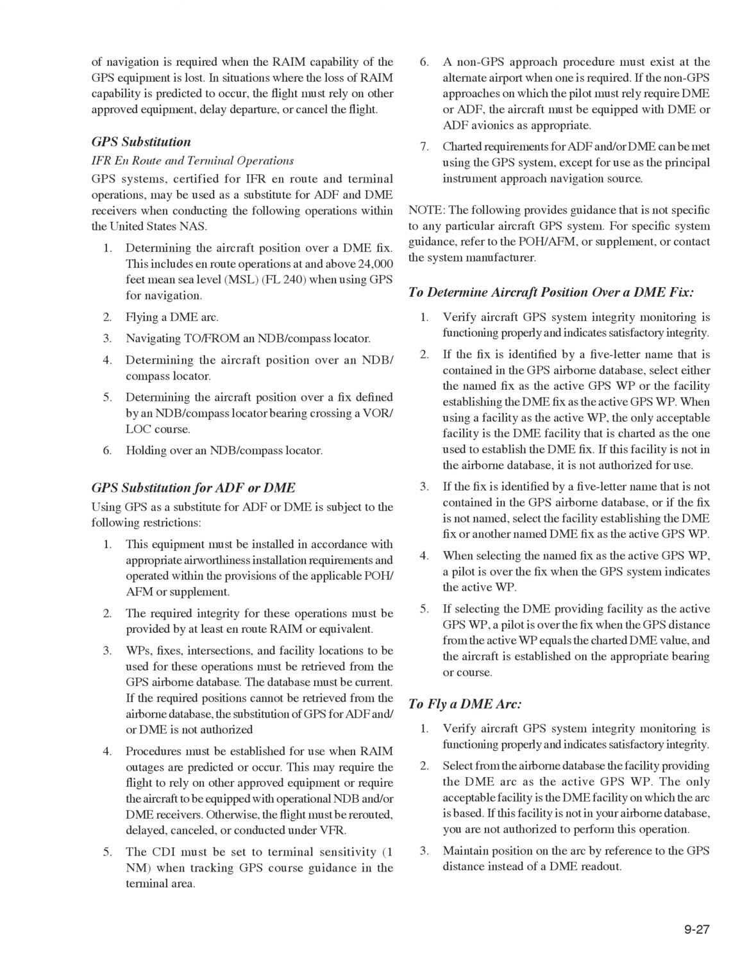1. Determining the aircraft position over a DME fix. This includes en route operations at and above 24,000 feet mean sea level, MSL, FL 240, when using GPS for navigation. 2. Flying a DME arc. 3. Navigating to/from an NDB/compass locator.